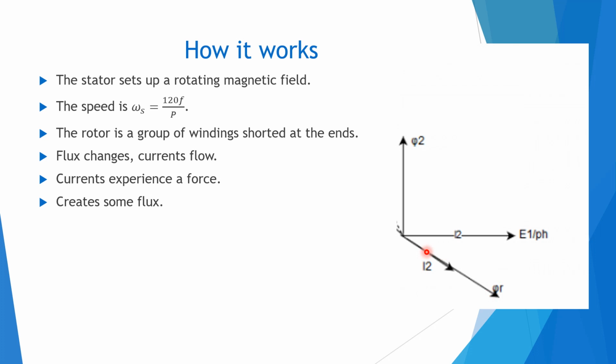What this means is that the angle between the stator flux and the rotor flux is 90 degrees plus delta. We have seen that if there are two fluxes having the same frequency, and these must have the same frequency, because the basic crux of a phasor diagram is that everything has the same frequency, right? Since these have the same frequency and there is an angle of 90 degrees plus delta, the sine of this angle becomes cos delta. So the torque is proportional to cos delta, right?